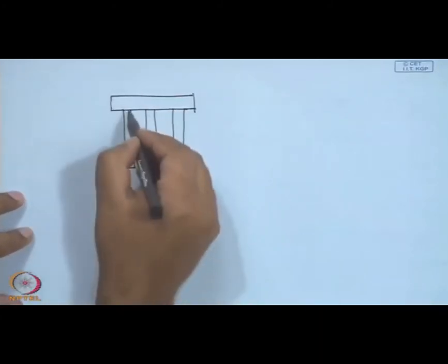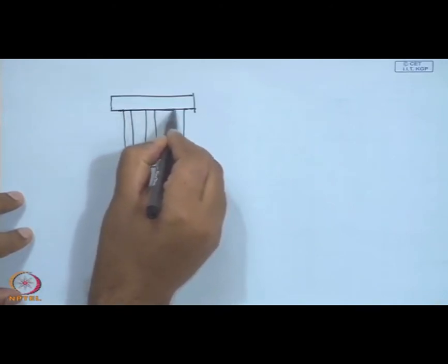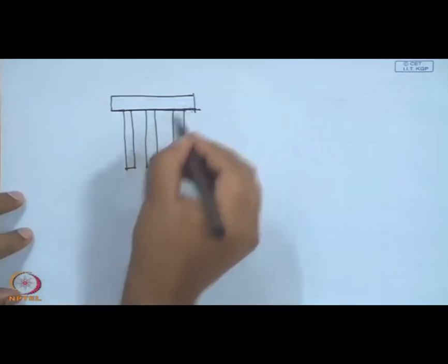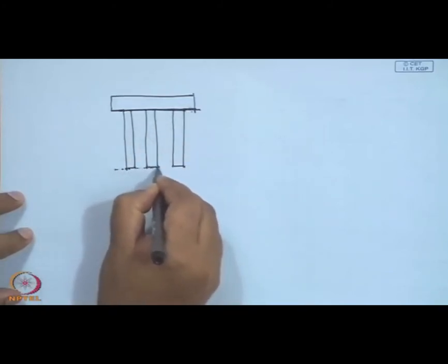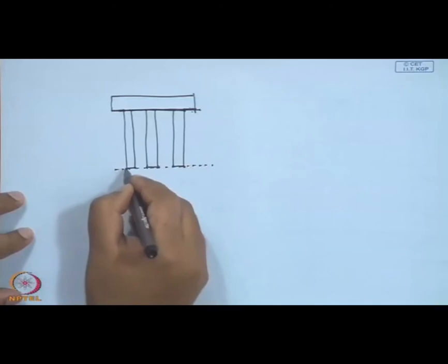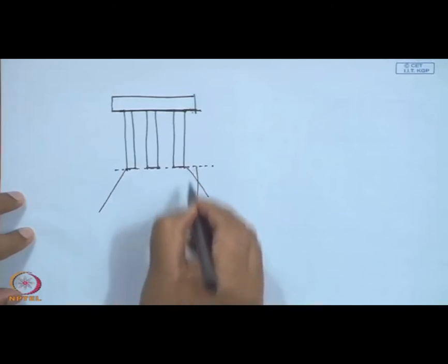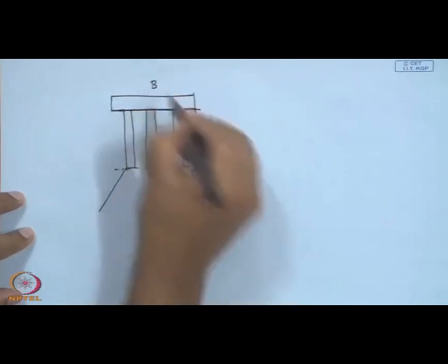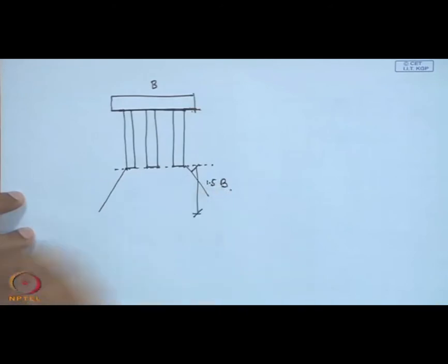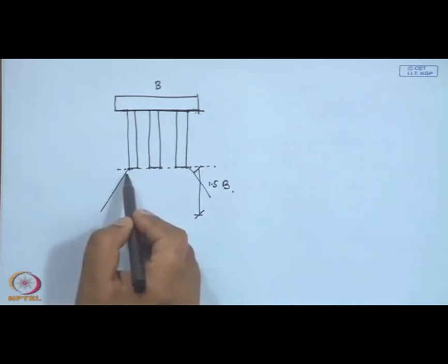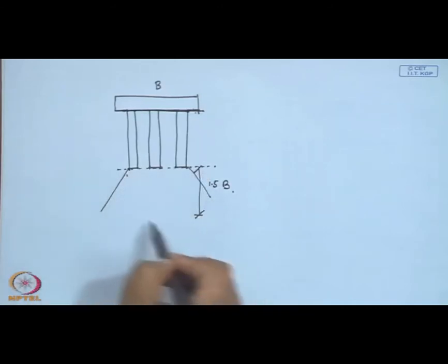So, generally it is saying that if this is the structural width of the pile cap, then from this bearing level we can go 1.5 times the width of the structure, that is, from the toe of the pile or bottom of the well we will go. So, that will be the minimum required depth of the boring.